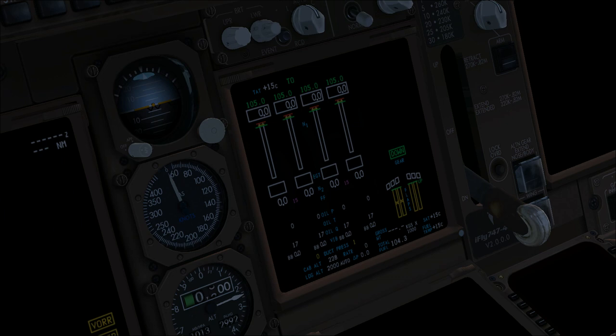When the flaps are in secondary mode, they are actually retracted and extended with bleed air and electrical power. This is when you actually lose the hydraulic power. In this case, we don't have the hydraulic power connected to the aircraft. We have zero pressure for now, and so we have the flaps in secondary mode.